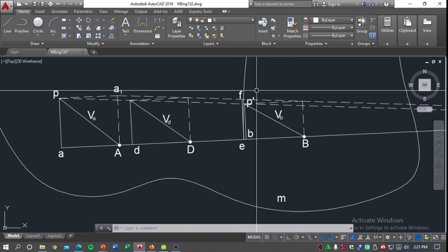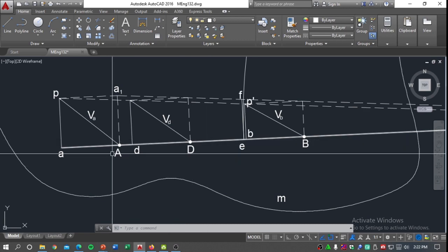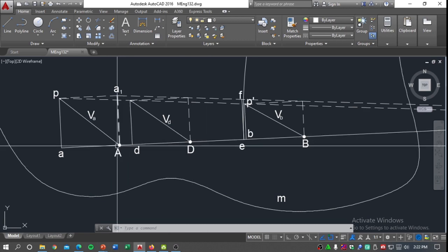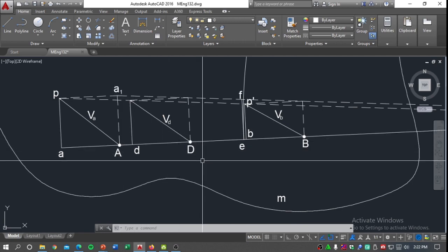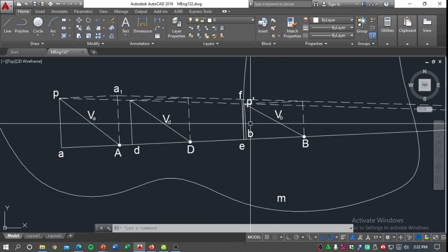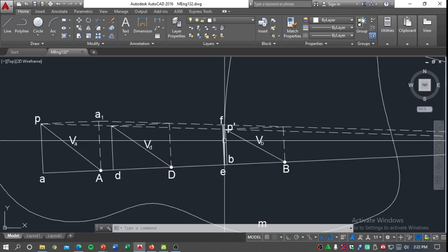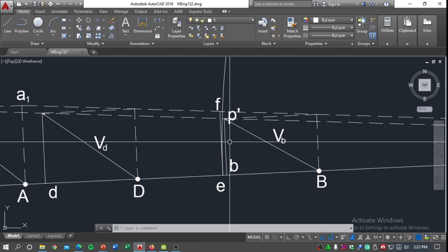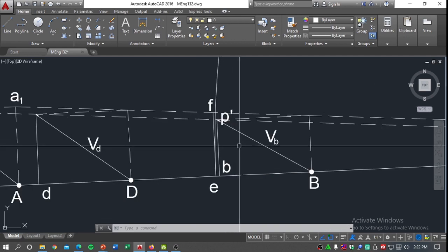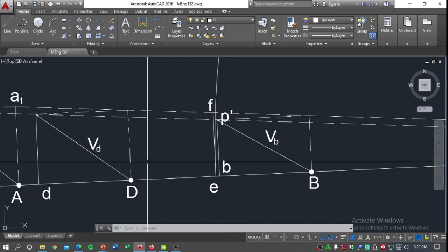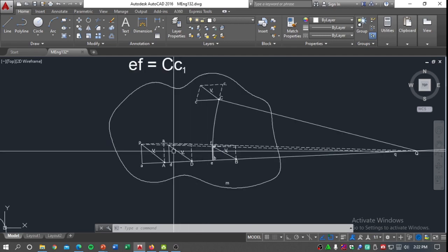So we projected that to point B along the line connecting A and B, and coincidentally it is collinear with point D. After that, we obtained the intersection of the projected perpendicular line with the direction of velocity BM, and thus we obtained the velocity vector VB.